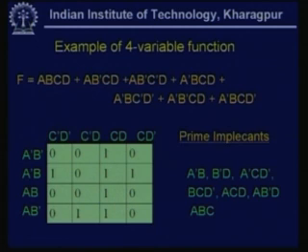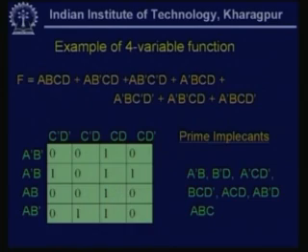That wrap around fashion, because always this can be a couple, but if possible I will always find out the largest possible group. So, that is why I will not take the couple, rather I will take the quad. Now, these two, this quad reduces to the B bar D. So, this is the B bar D.